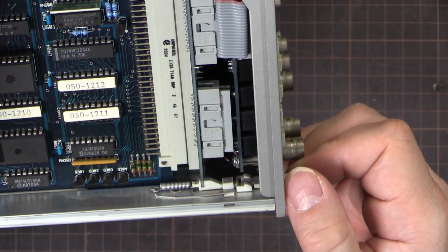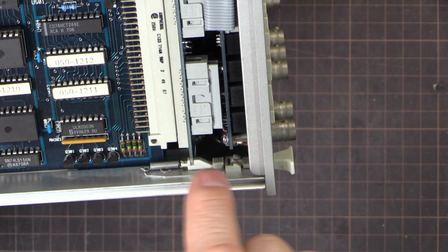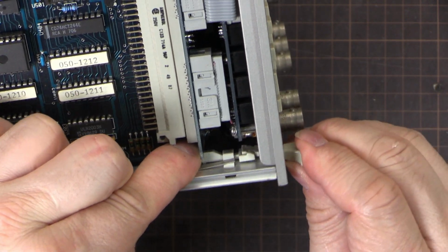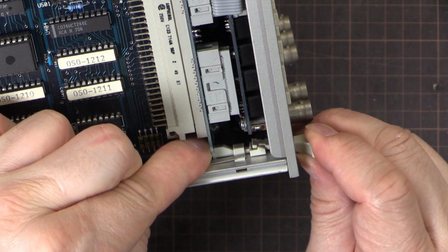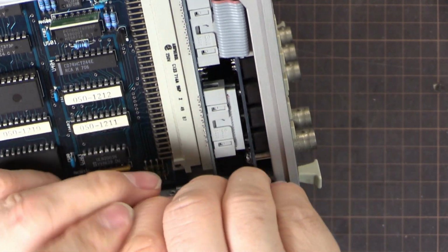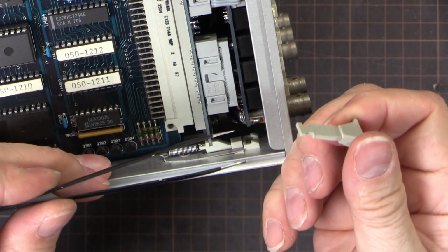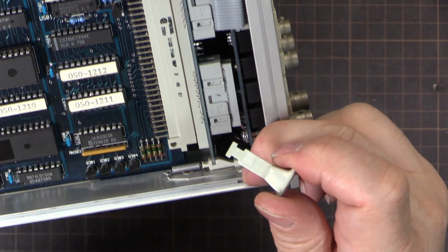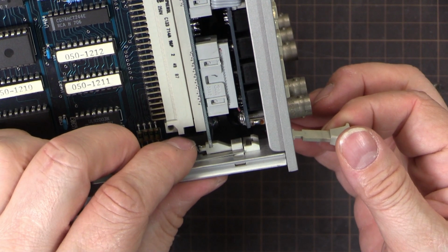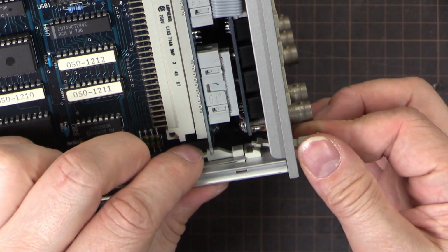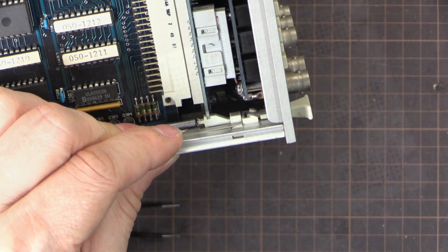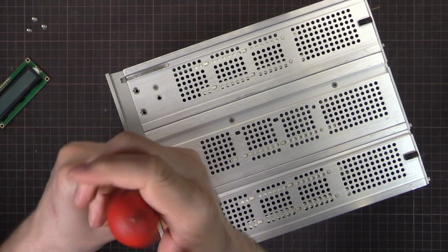So what we need to do is release this part here from the inner section there. If you pull it forward, hold it there with your finger, and push it back in, hopefully you can see there it's kind of popped up a little bit. Get some tweezers and get underneath there, and if you lift it up carefully, it'll come straight out. Don't bend it too much. You don't want to break it, but just a little bit of a flex and it'll come out. And then to put it back in, put it in the hole and push it forward, and it'll sit back straight in there like that. Easy peasy. So we'll get these out.